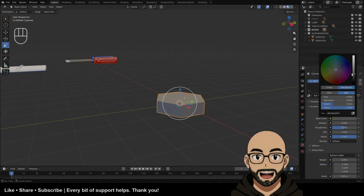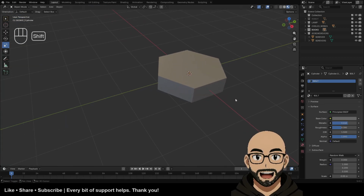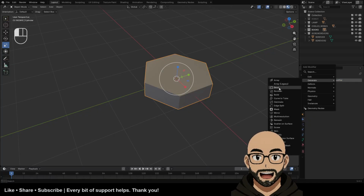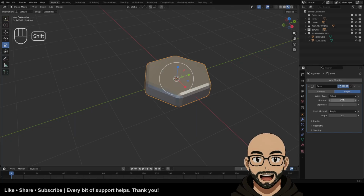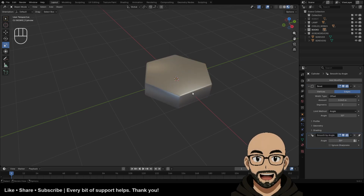The new material is called bolt, for a metallic. Roughness down, maybe too metallic, but there we go. If we add a bevel to this, so we go modifiers, add a generate bevel, and we get some nice edges, so we can pick up some of that reflection, and we're going to hit shade auto smooth.